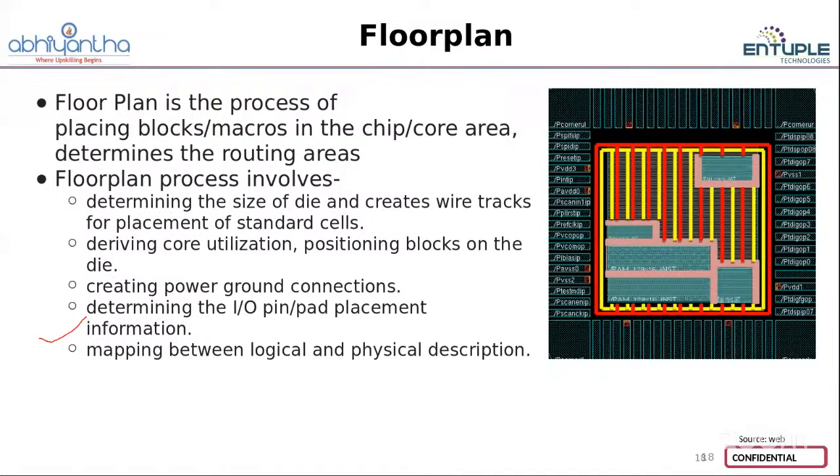That is the padding method. Here you can see the IO pads are added with various tracks. Each and every IO pin in the gate level netlist you generated will get mapped with the IO pads of the technology library. In that, you need to understand how many IO pads and corner cells are required, and whether any macros are required.